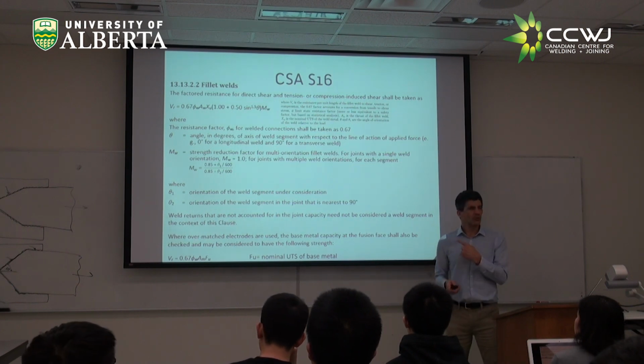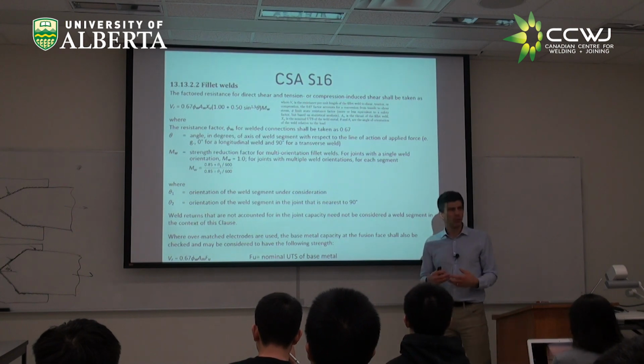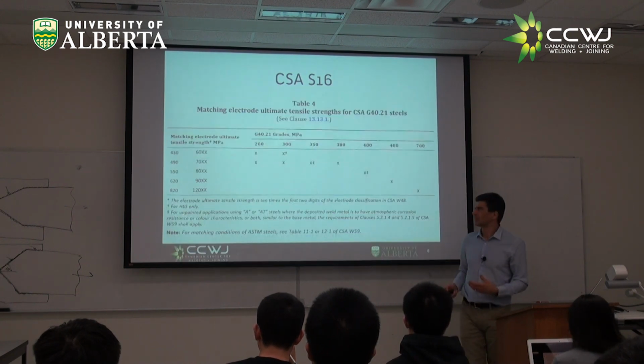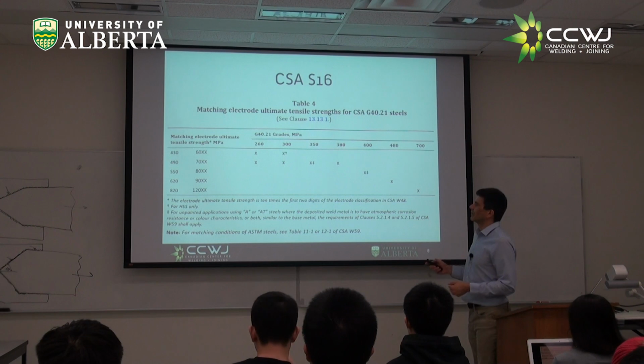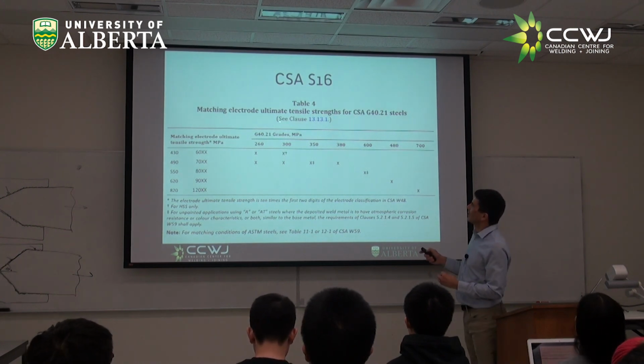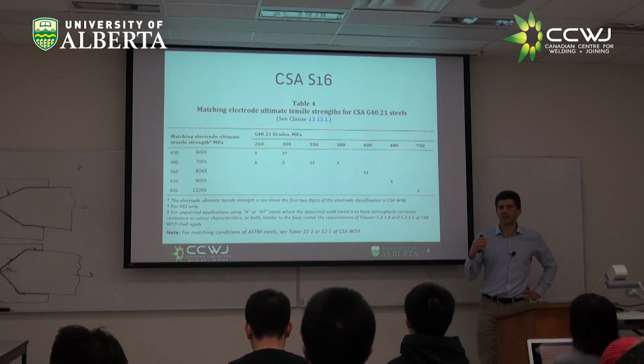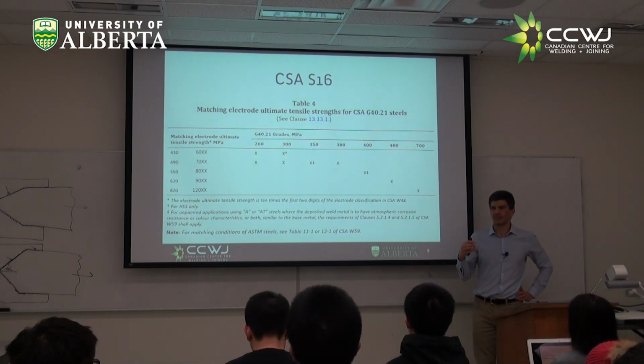All right? So I want to show you those tables, which will be in your formula sheet in the exam, and are tables from the code. And this is the way engineers work with these things. So you design the welds for UTS. Okay, first, here is the matching electrode and with the UTS of the plate. So when we say matching, we talk about matching UTS.